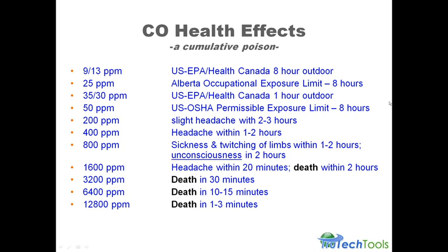Are you saying no soot with natural gas or propane? You can get soot with natural gas and propane. Typically not. Typically, if we have soot with natural gas or propane, we have way too much fuel and not enough air. But under normal conditions, never any soot with those two gases. Typically, we'll have a little bit of soot with oil.